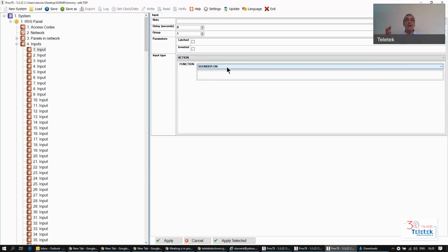when there is fire. But remember, you can set up delays for the sounders, delays that are used to investigate the zone and see if it's a false alarm. You don't want to, upon receiving an event, fire or evacuation, activate everything right away, because then it makes those delays for the sounders useless. So imagine you get a fire in zone number 1 that has a 5 minute delay for the sounders. The security guard goes there, investigates, sees the actual fire, and presses a call point to bypass the delay and activate the system into fire mode or evacuation mode.